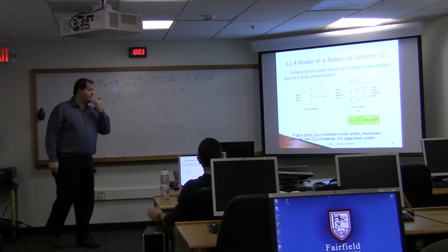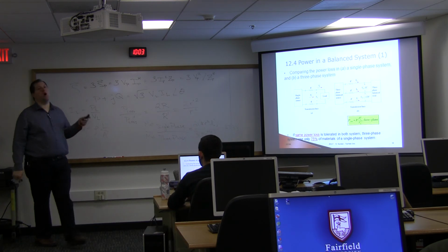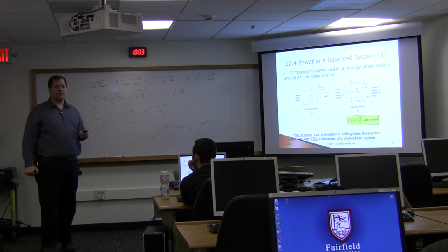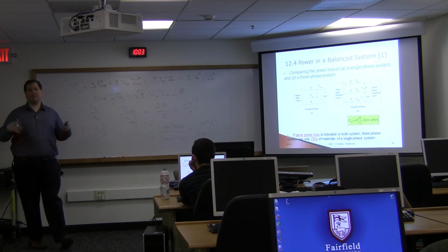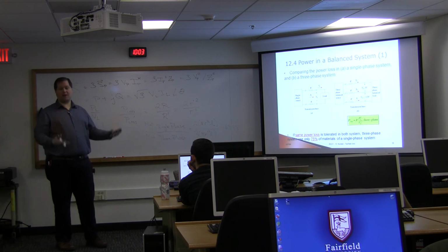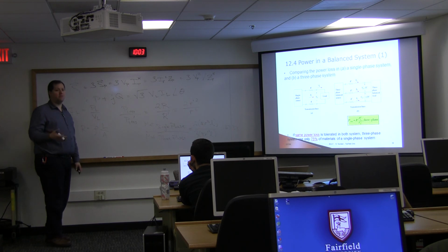And even more than that, imagine if all of the power systems in the country were trying to run single phase. They would all need 33% more copper. What would that do to the price of copper, right? There would be a huge demand for copper. We wouldn't even hardly be able to mine enough copper, right? And so the price of copper would go up and it would cost even more, right? So the economics of it are incredibly favorable to actually use three-phase power systems, right?